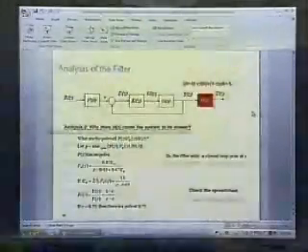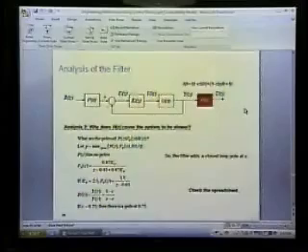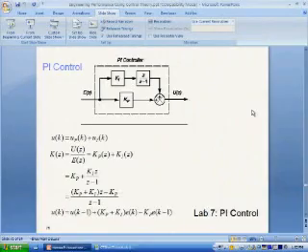And the response now looks a lot like the integral controller. Yeah, it does. It has a similar kind of effect. So what we did is we tried to sort of shortcut all that we were doing with the integral controller. So the moral of the story is, well, why don't we just go straight with the integral controller? This one doesn't lock on to the value of R. Exactly. Well, you have to play with it. You have to design it so that it will. You have to think about the precompensator and what that P of Z should be, what the constant should be. Okay, so that's the moral of the story. You could go straight with the integral controller, or you could do these things in combination.